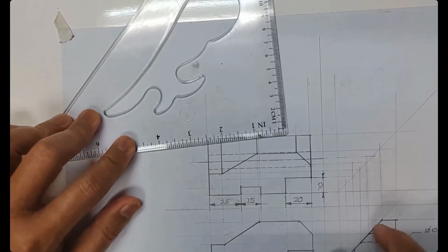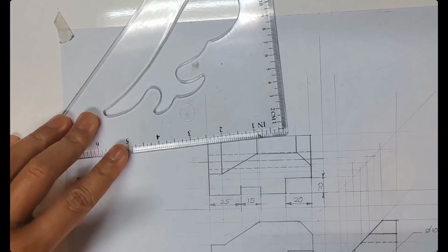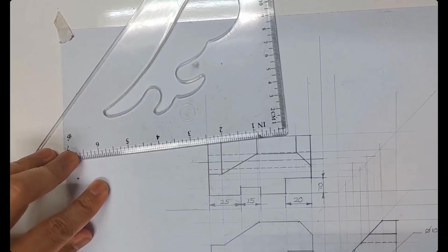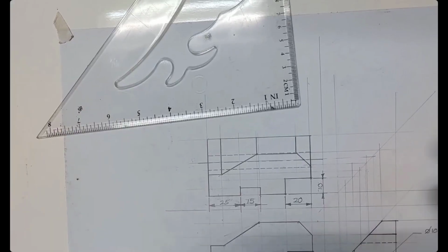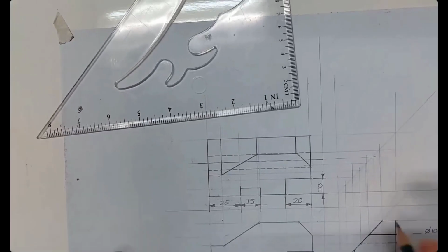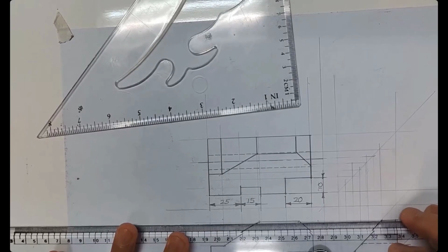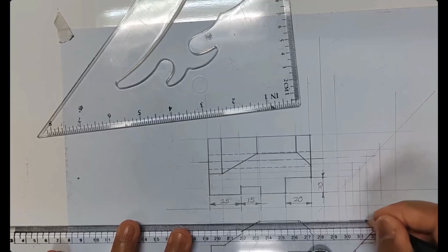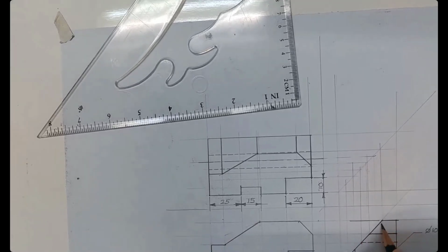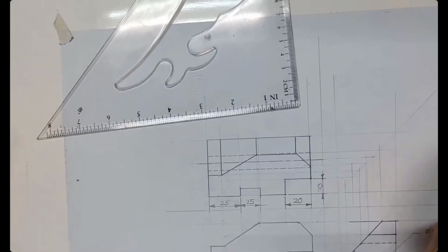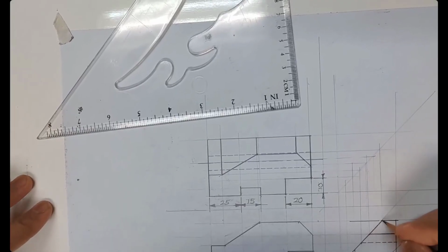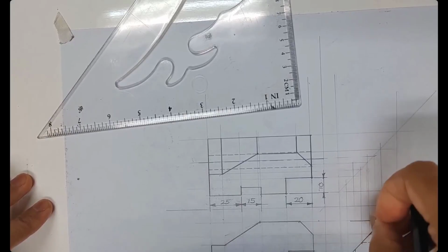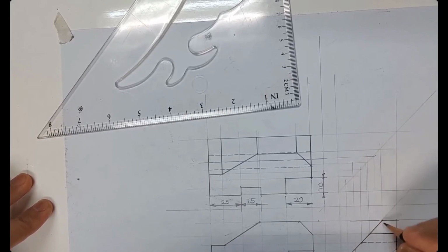Side view shows clearly the features of the 45 degree cutting angle. So you have a 45 degree, you need to show this one. So this is an angular dimension. I have a corner, so it means I have the extension line. Extension line is not cutting at the corner. We have a gap of 10, so you clearly make the extension line. We have a gap. Now I didn't have a compass. You have to make compass, this will be your center point.